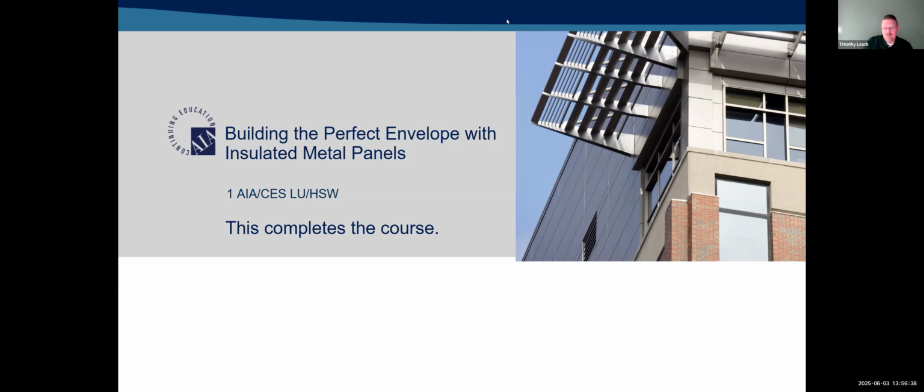A really cut up building, with a lot of facets and joints and that sort of thing. Maybe there's some situations where it'd be better to use just other types of materials. But whenever I talk with folks, I say insulated panels are great whenever they're the right application, and there are certainly situations where it's not the right application.